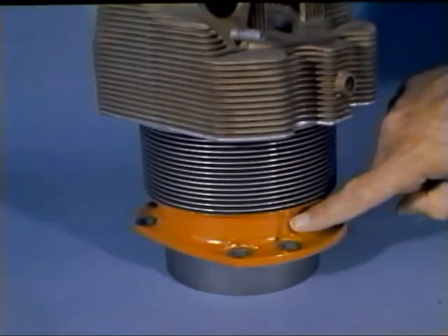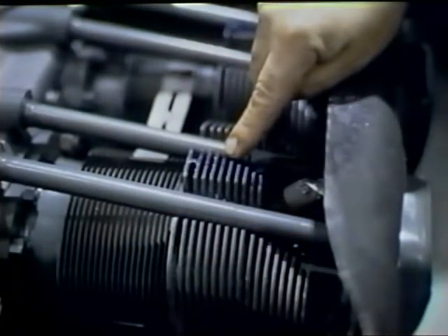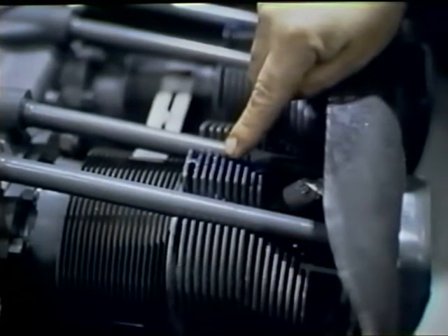The inside of the cylinder barrel may be plated with porous chrome. This special surface contains thousands of tiny cracks which hold oil to lubricate the piston during operation. Chrome-plated cylinders are commonly identified by a band of orange paint around their base or by painting some of the fins orange. Other cylinder barrels have their walls case-hardened by a process known as nitriding. These cylinders are identified with blue paint.